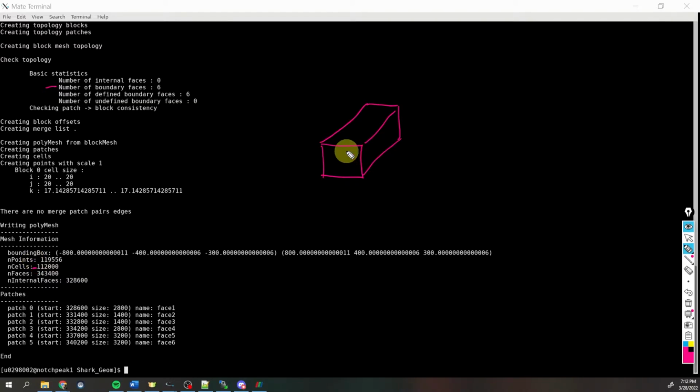From a couple of other parameters in there, I've split, say, this direction up into 80 different sections, and here is like 40, we'll say, so that there's little subdivisions and even smaller cubes. This is the part of the meshing process that we also would have done with ANSYS.